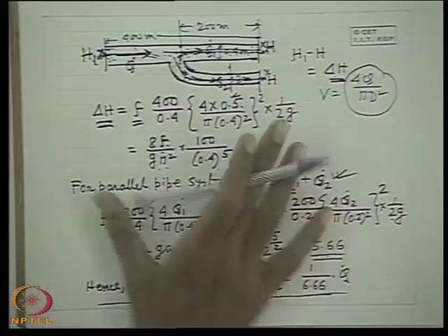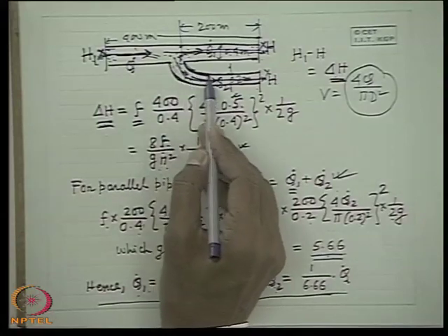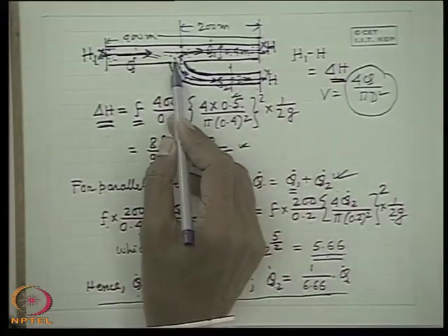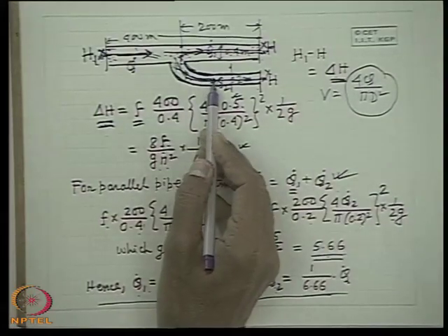I am defining the theoretical aspect of it. In practice, if you make a parallel pipe joint, there will be some bend of the pipe, and the pipe goes like that. Due to that bend, there will be some losses. In a problem, if that is not told, you cannot find it.